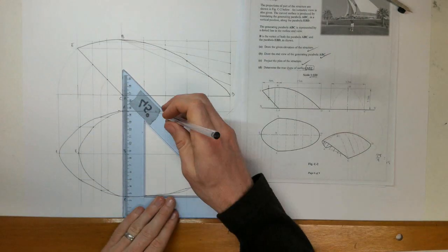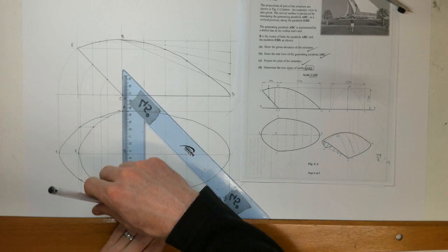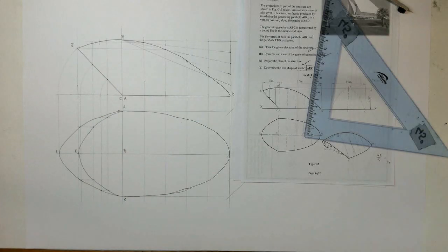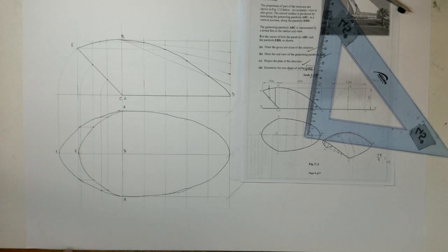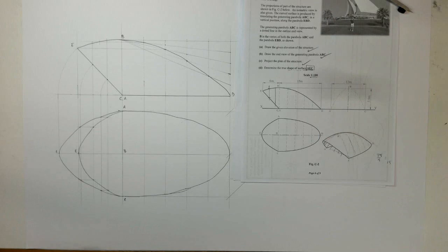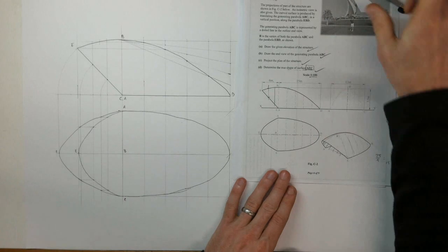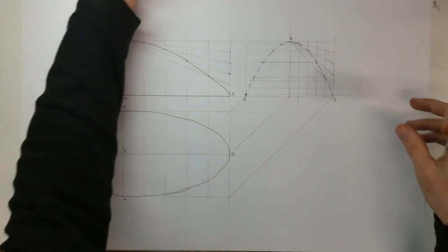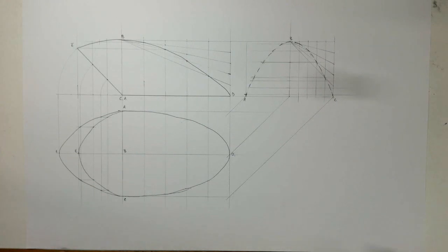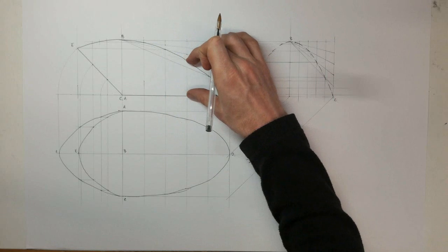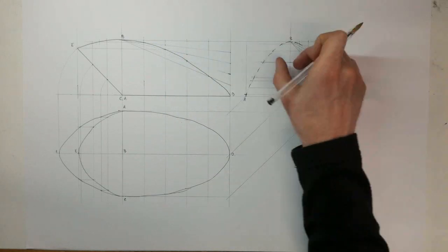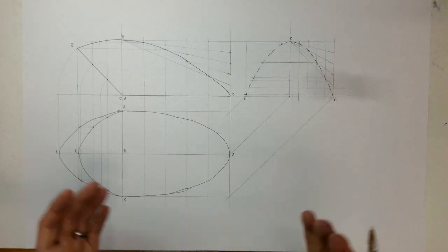And we won't have an edge there just to show it. So that is the true shape of surface AEC. So include there, just to show the final solution. There we have it. So the key thing is that bit, understanding that vertical sections is just decreasing the height of our parabola and finding the width then of that corresponding shorter parabola.